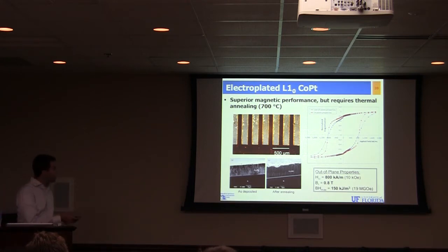There's some columnar striation. If we go into more detail on a cross-section, you'll notice some microstructural columns form out-of-plane, and so this also helps give some shape anisotropy, not the full demag that you might expect for a traditional thin film, where that out-of-plane magnetization curve might be very flat.